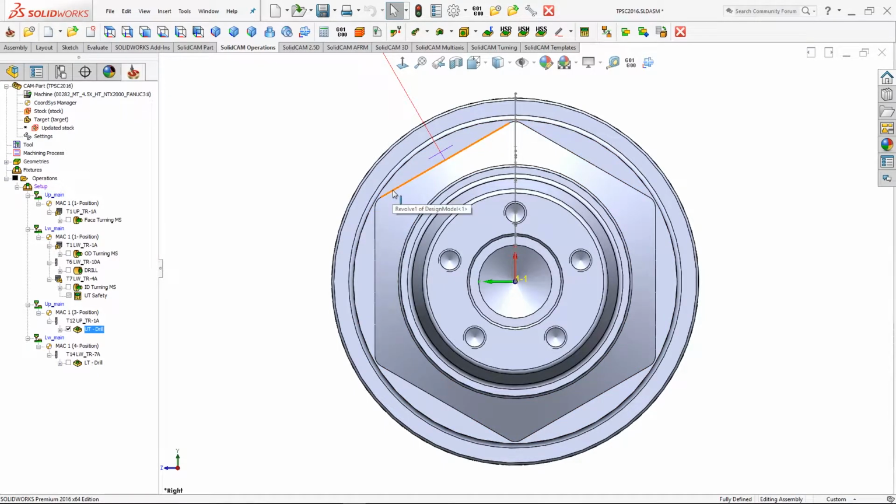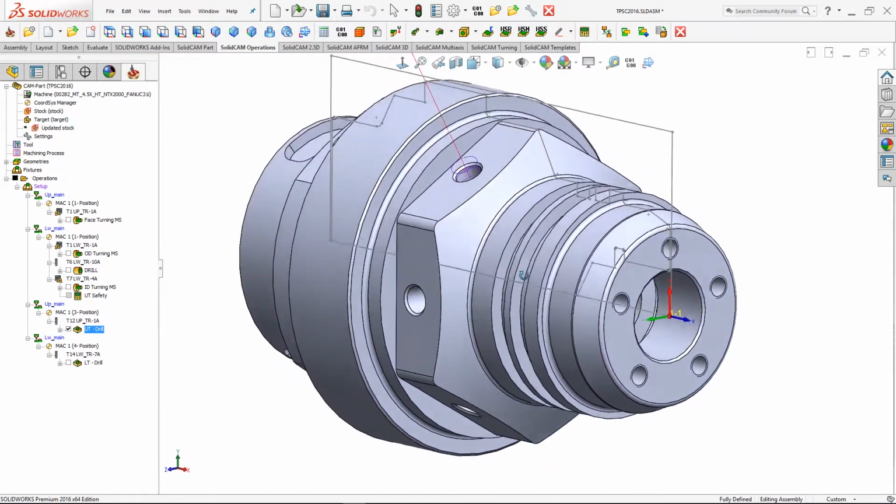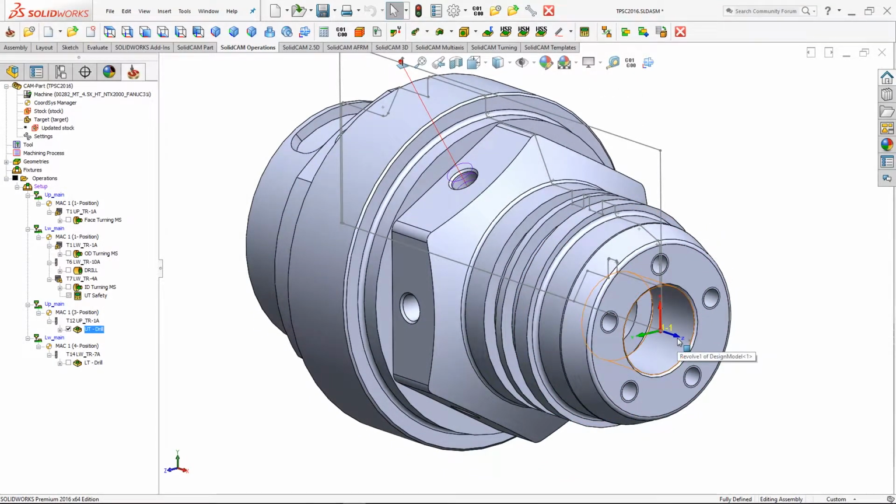Now many of you might ask which angle this should be on the machine. From the machine, the parameters on the controller can be different, and a different angle of the output can be applied. In most machines, this angle is positive 30 degrees. If you take the z-axis with the right hand rule, the fingers will show you the positive direction of the z-axis. Therefore, this hole is actually on the z 30 degrees.